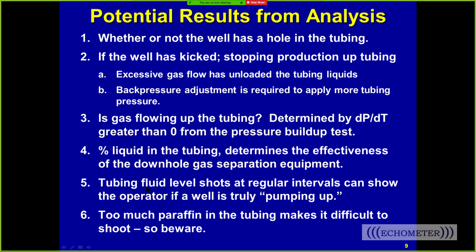If your tubing unloaded and you are trying to decide, do I call the water truck to fill the tubing up with water to regain pump action, then you can shoot fluid levels and see if the liquid level is gradually coming up as you pump the well, and you don't need to call the water truck to reload the tubing with liquid. If you have a lot of paraffin being produced in this well, it's usually hard to shoot down the tubing because paraffin globs are blocking the acoustic pressure wave, and you can't really use this technique very well.